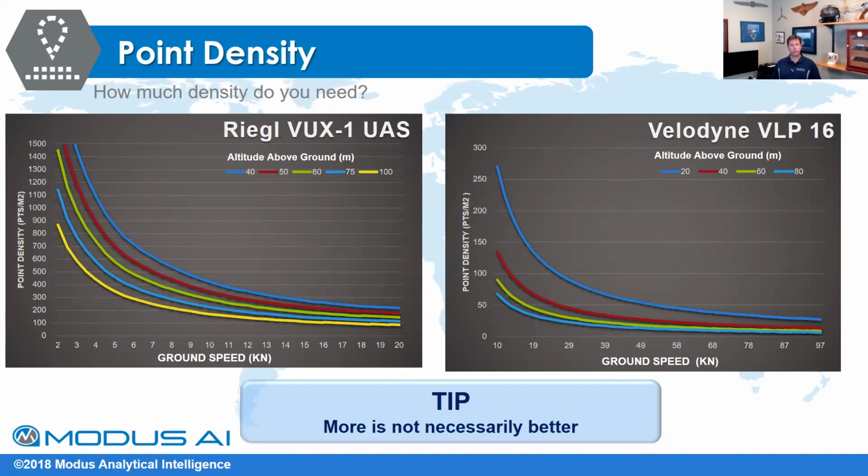So again, knowing those data standards is really important, and we'll go over a little bit more of that in detail. But the biggest thing is not to over collect, because if you over collect, then you're going to spend a lot more money in labor and processing costs on the backside, down sampling your data sets and tiling them into smaller chunks, which with drone data, since you're covering small areas, you shouldn't have to. But if you're collecting such large volumes, you'll run into those schemes that you typically see in aerial type